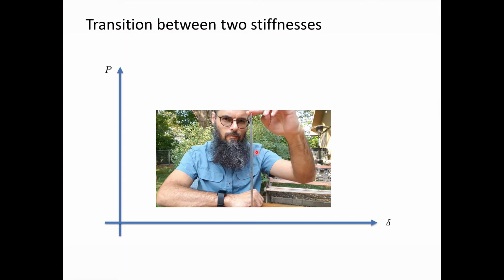This next plot is really a simplified characterization of it. My fingers are not a very sensitive load sensor, and so this is just an approximation. So initially it's really stiff. It behaves like a compression member, and there's not really any elastic instability behavior. It's basically just the stiffness of the cross-sectional area. So if we think of the formula where the deflection of a member under compression or tension is equal to P over the stiffness, the stiffness is EA over L, basically.